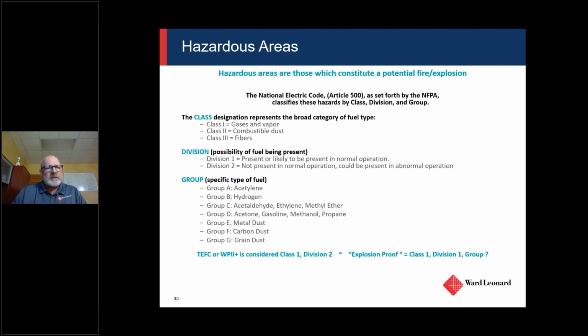And then on hazardous areas, there is a UL certification and UL design of a motor, Underwriters Laboratories, and that's really what these are talking about. So when we talk about Class 1, Div 2, group whatever, that's what we're talking about, right?